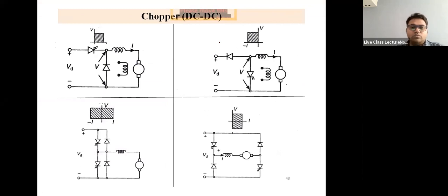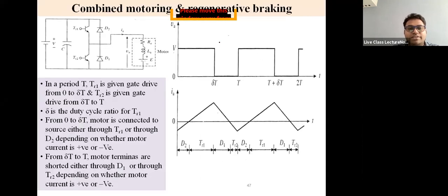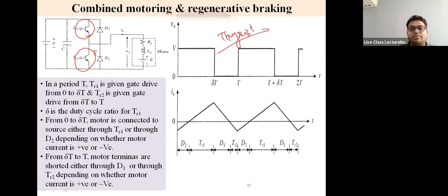Okay. So here you might be seeing in some books that they're using thyristors as the switches, or as the case may be, here it is shown as the BJT. But in the true case, I must tell you, thyristors are never used in DC circuits, most of all, and never in DC-DC choppers. Because if you turn it on, it is extremely hard to switch it off.